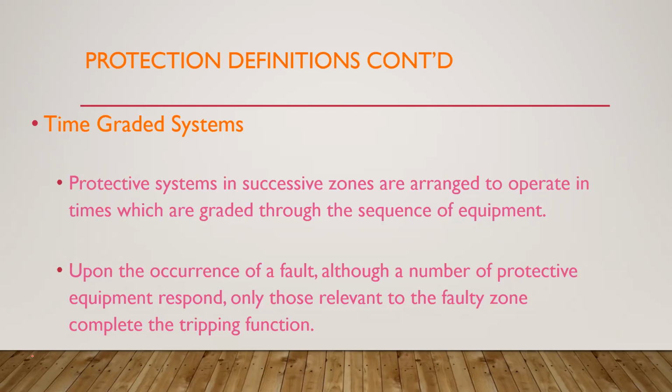When that tripped, the power that was now being supplied to the southern part of the country had a significant shortfall. And now a significant amount of power needed to be supplied from Bogue. Now, Bogue can't supply that. So that tripped also.